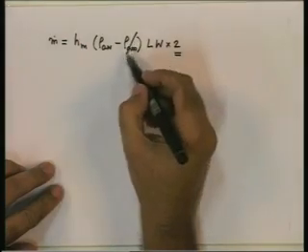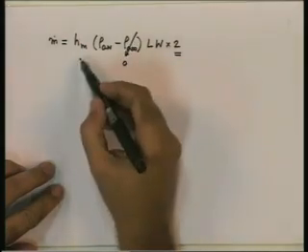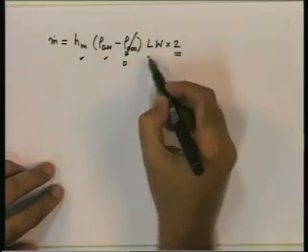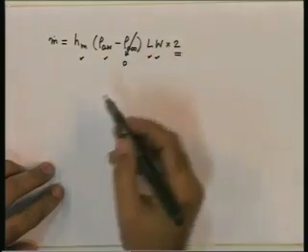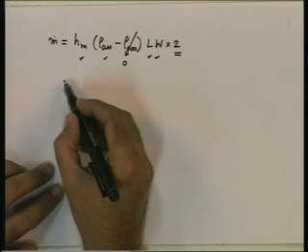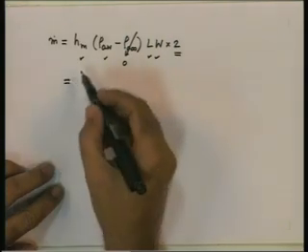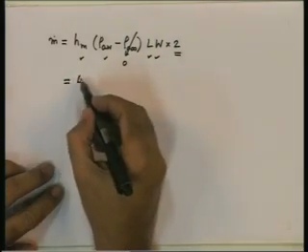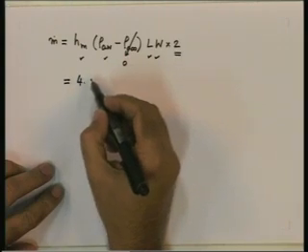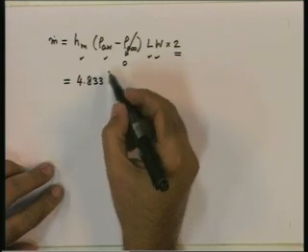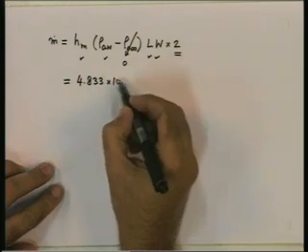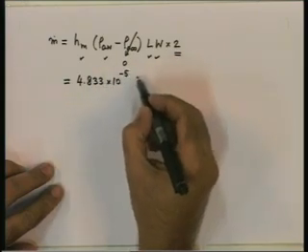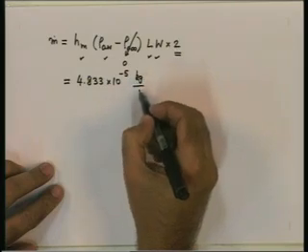This is 0, and we have the values for Hm, rho A W, L and W. So, if you substitute in this, you will get the mass flow rate or mass transfer rate, that is the evaporation of water, rate of evaporation of water from either side of the plate is 4.833 into 10 raised to minus 5 kilogram per second.